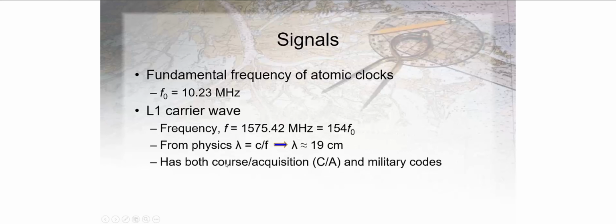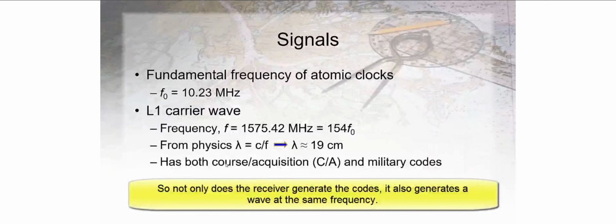So in other words, if you think about it from the point of view of an EDM, it's doing the same procedures, except that the receiver has to generate the signal rather than having a splitter that takes the original signal and splits it so that one goes out to the reflector and comes back. We don't have that capability of sending to the satellite and getting the signal back. What we do is we actually just generate our own signal at the receiver.